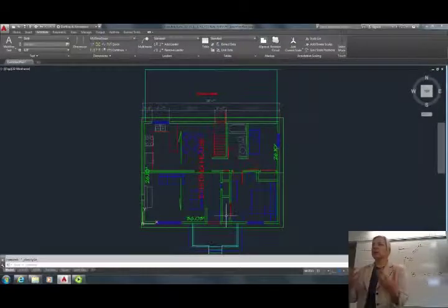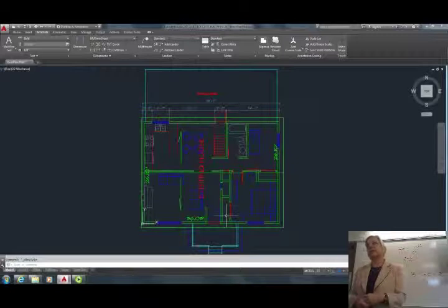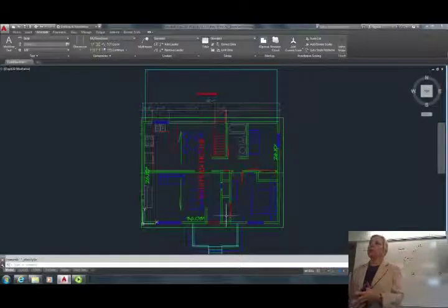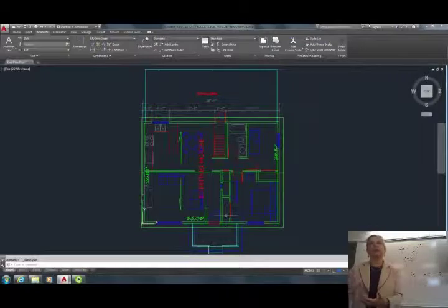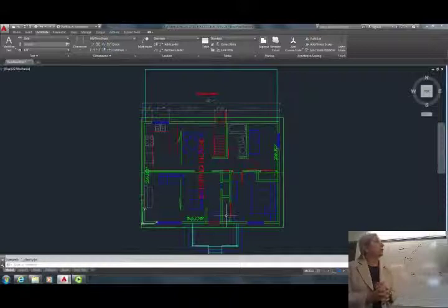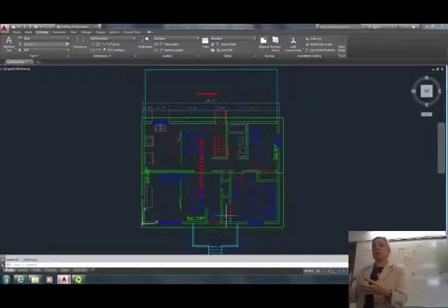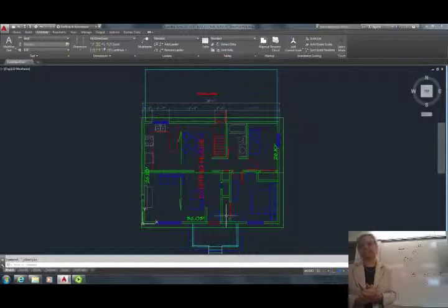I like control. I want a certain look. I've always dimensioned my project to the opening, so the dimensions that had to be purchased, if on drawing, then the builder is obliged to provide what's on the drawing. So my client would always get the windows that I sized. So the height would go on elevation view, but the openings would be dimensioned here, and then the comprehensive set of drawings would actually have a drawing summary with a table specifying a door and window schedule.